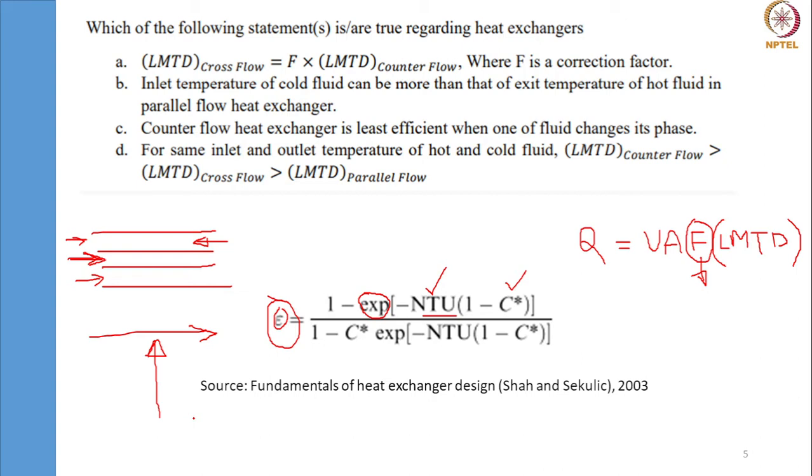So there is a 90-degree angle between the hot and cold fluid. So in these three configurations and many more configurations, we are going to learn the effectiveness-NTU relationships. Why I have told you about this parallel, counter, and cross flow is that for different arrangements, the effectiveness and NTU relations are different. So I just wanted to ensure that that point is also stressed upon.